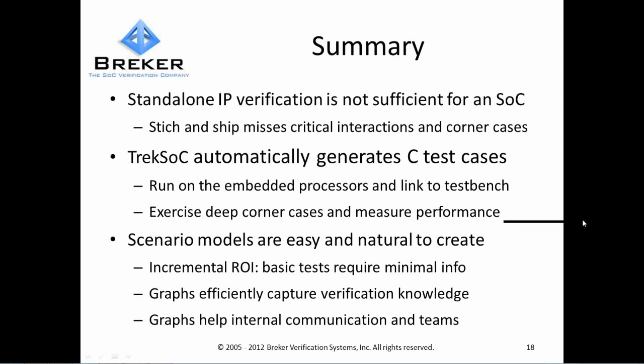See, in an SoC, the problem starts to get more complicated, right? Because you're trying to generate these embedded C programs that are trying to get all these IPs to go concurrently with the right randomly selected timing edges to go after corner cases in the system. And I think this is pretty hard to hit with the technologies we have right now. But philosophically we're still doing constrained random verification.